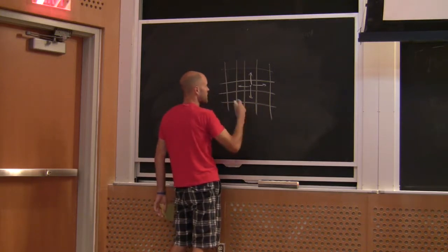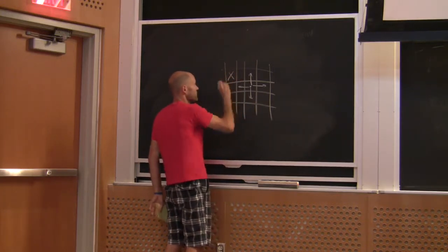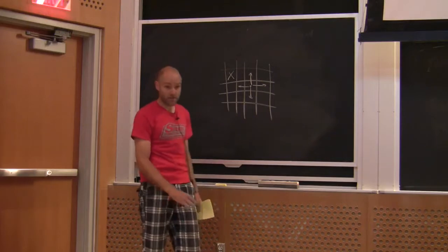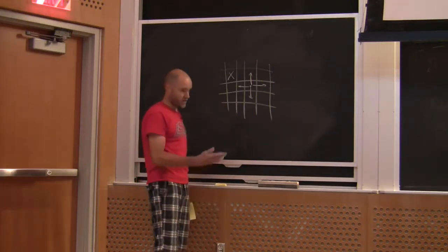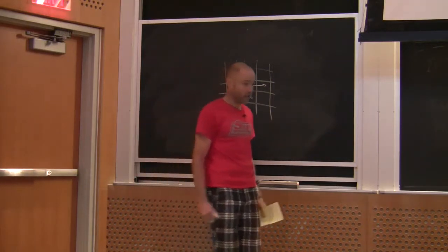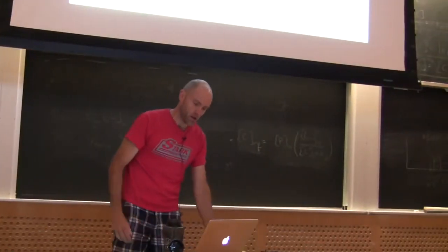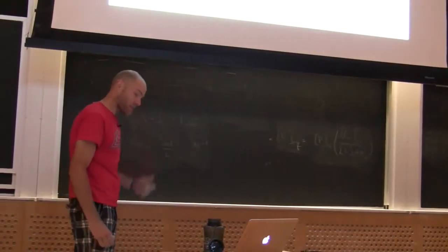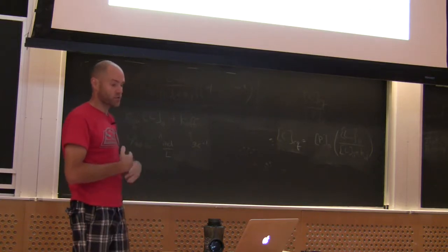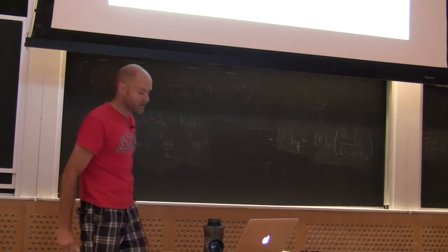Some of these grid cells are marked as don't go there. There's a high cost associated with being there, and there's going to be a goal region. I think you can imagine what the robot should maybe do here, but let's actually watch how the value iteration algorithm proceeds to solve this kind of problem.